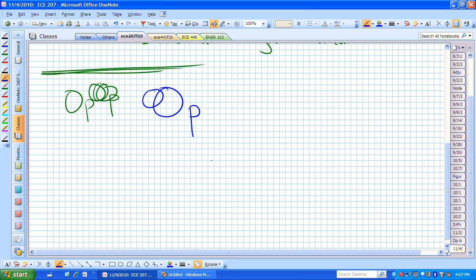But if we go back to the relationships that we had, which was just this one, now I have to learn how to do origami to lecture, folding paper. If you look at this, now you have Vn is equal to R sub I times I sub 1. If you solve that for the ratio Vn over I sub 1, what happens? You just get R sub I out, and that's all we're saying here.